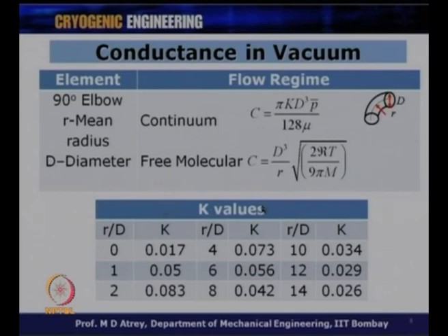and for different structures, therefore, for different pipes, for different joints, for different curved elbows, etc., you calculate the conductance in this way, and then effectively you will calculate, if there are pipes in parallel, if there are pipes in series, the overall conductance of this combination of pipes. In addition to this, we will have several couplings. We can have several non-characterized kinds of items which could be placed in position, or pipes of different structures also could be placed, and then correspondingly you will have a very big table that is available in the literature, which you have to look for, and you can get the conductances for those particular structures which are employed to connect the vacuum pump to the system to be vacuumed.